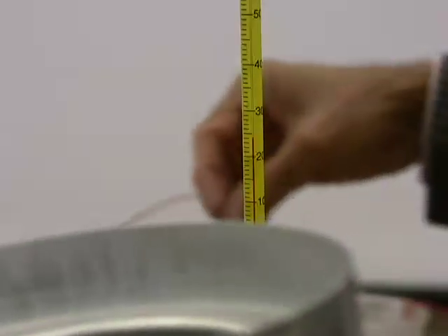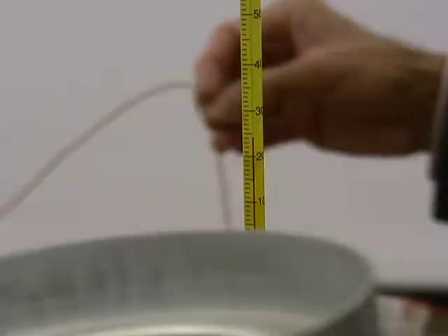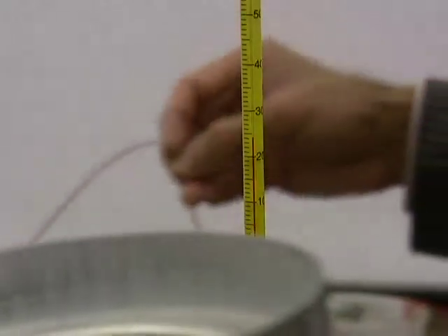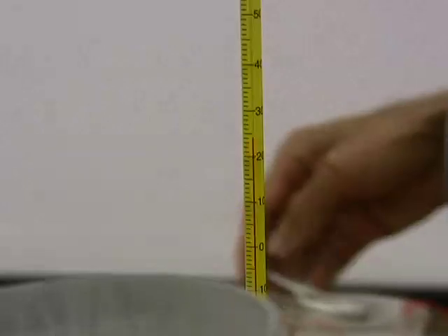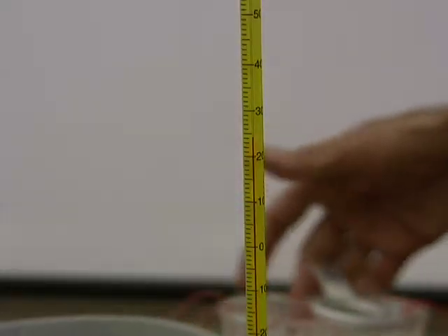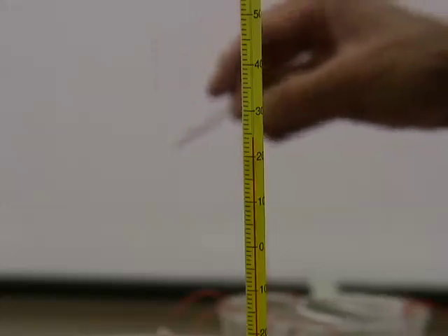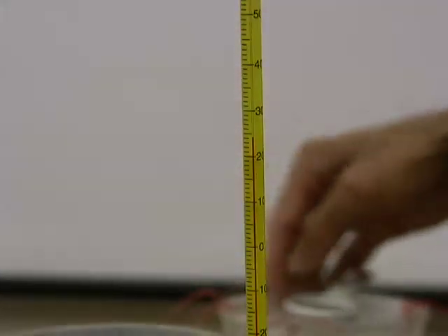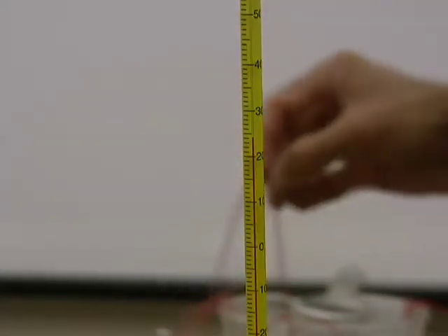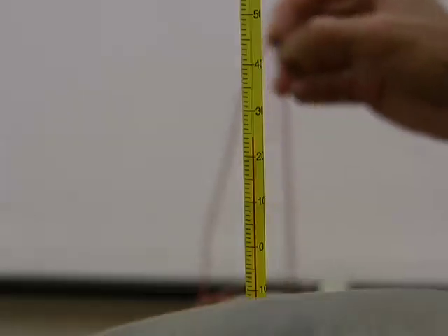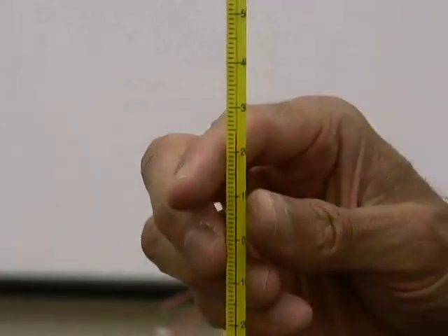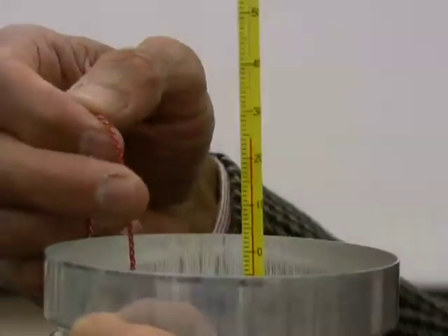I'm going to transfer the first copper sample to the water, and we need to measure theta3. Okay. Now, I need to do that very quickly without heat getting lost. Now, there we have, and I want you to measure the final temperature.